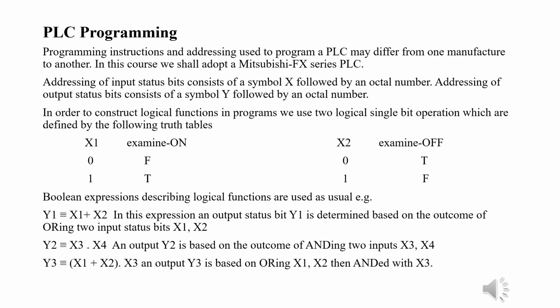Programming instructions and addressing schemes used in PLCs depend on the manufacturer of the PLC, and they can change from one PLC manufacturer to another. In this course, we will adopt a Mitsubishi FX series PLC. Addressing of input status bits in the Mitsubishi FX series is based on a symbol X followed by an octal number, and addressing of output status bits is based on a symbol Y followed by an octal number.